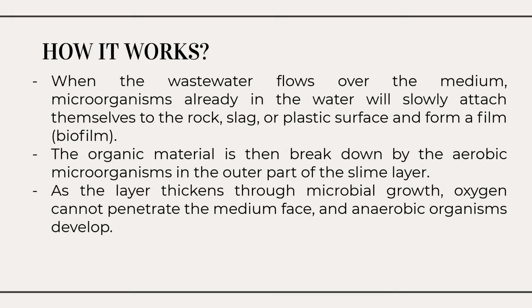So next I'll be explaining how it works. As the wastewater flows over the medium, microorganisms already in the water gradually attach themselves to the rock, slag, or plastic surface and form a film. So this film is called biofilm. The organic material is then degraded by the aerobic microorganisms in the outer part of the slime layer.